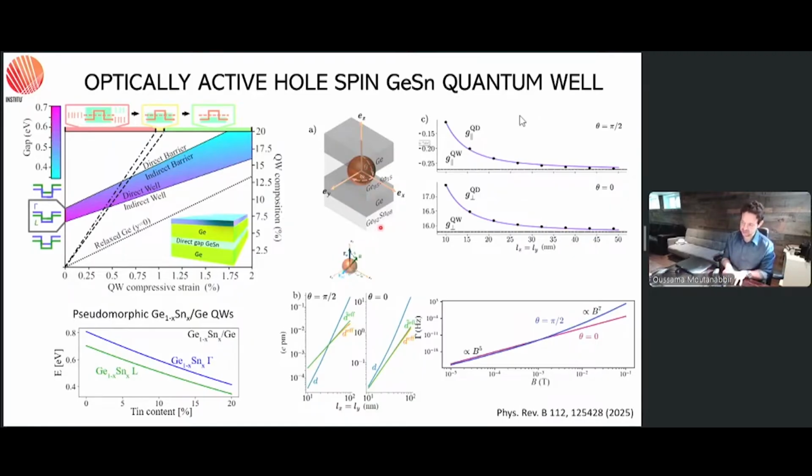I will give you a quick idea how we grow germanium tin in general, because the key is to achieve sufficient relaxation in this buffer layer. After that, we control the growth with germanium that will be tensile strained, and the layer should be thin enough so you don't create dislocations, so below the critical thickness. After that, you switch to germanium tin growth at 15%, at much higher composition, and you cap with germanium.